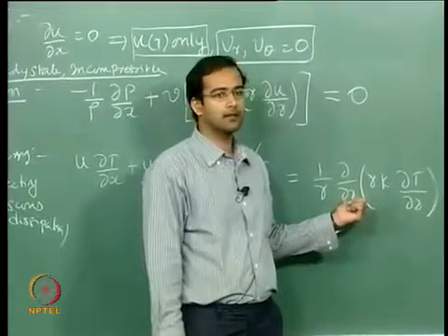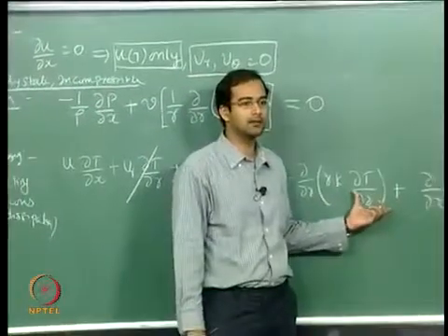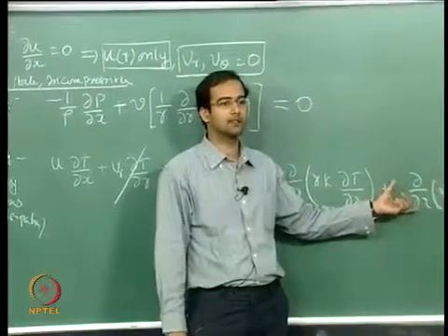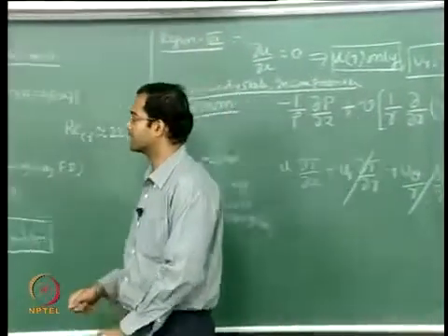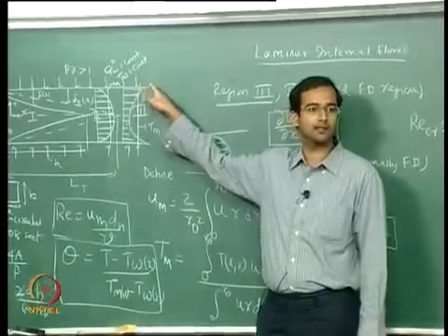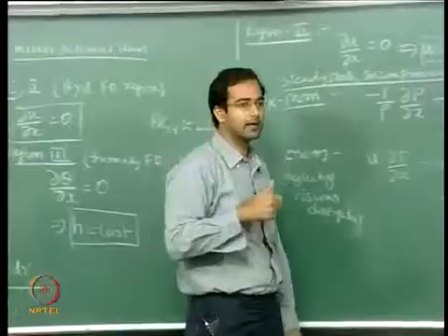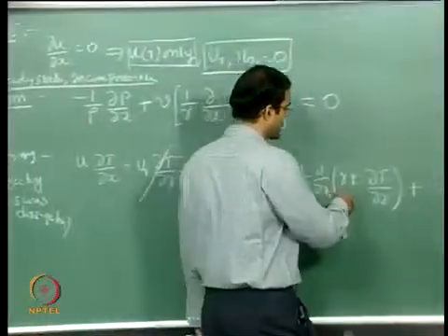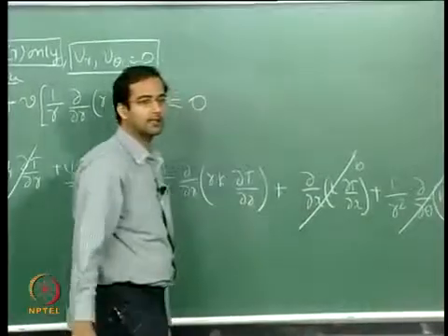But once again we will make an approximation that compared to radial conduction, axial conduction is very minor, because if you look at the profiles of temperature, the gradient is dominant along the r direction, therefore the diffusion will be much more pronounced in the radial direction. So compared to the radial conduction we will also neglect the axial conduction term.